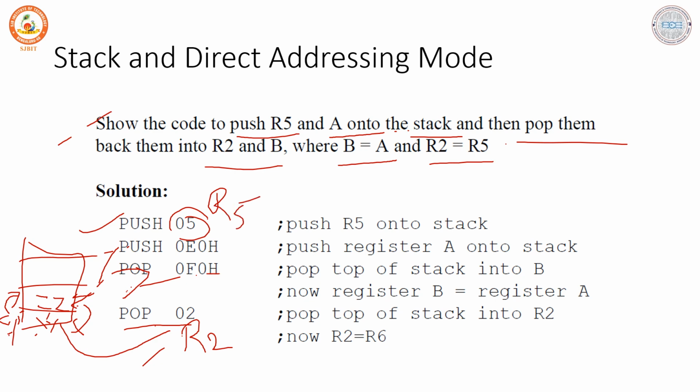As I told you, the register banks will be addressed with R0 to R7. I can make use of each and every register bank. Here there are 4 register banks, and each bank starts with 00 to 07, that is R0 to R7. So for any address location with respect to the register, I can move the content or store the content.